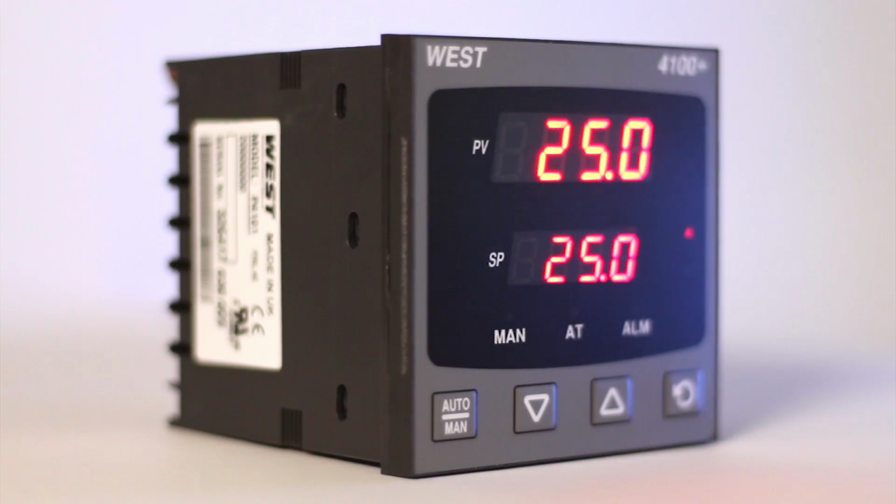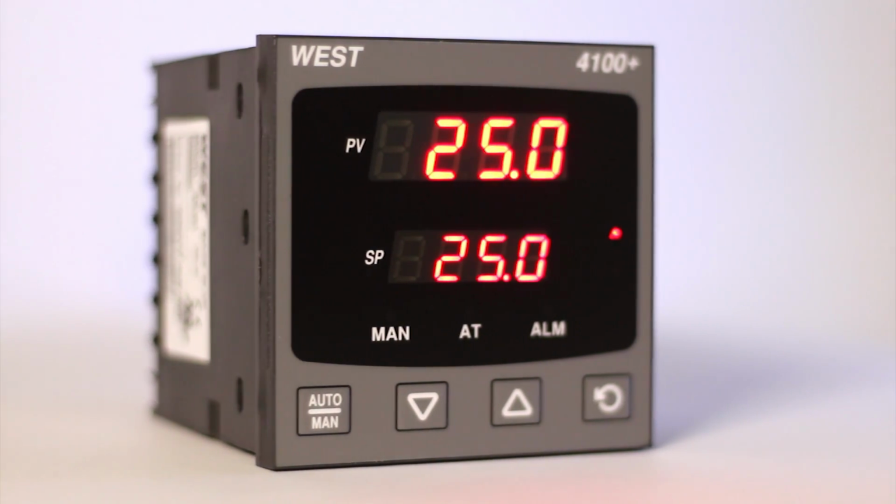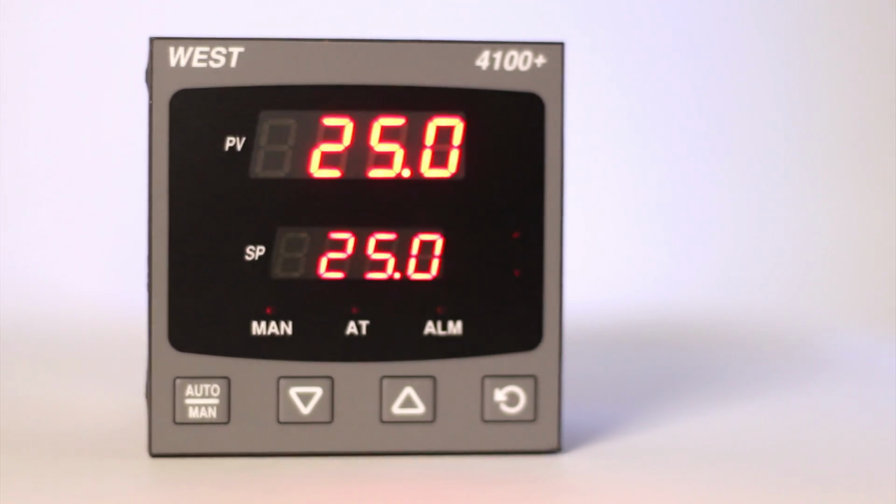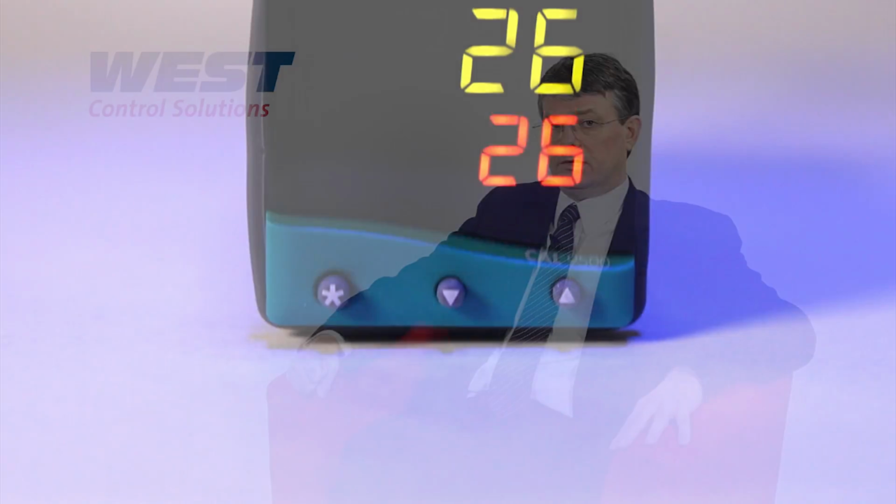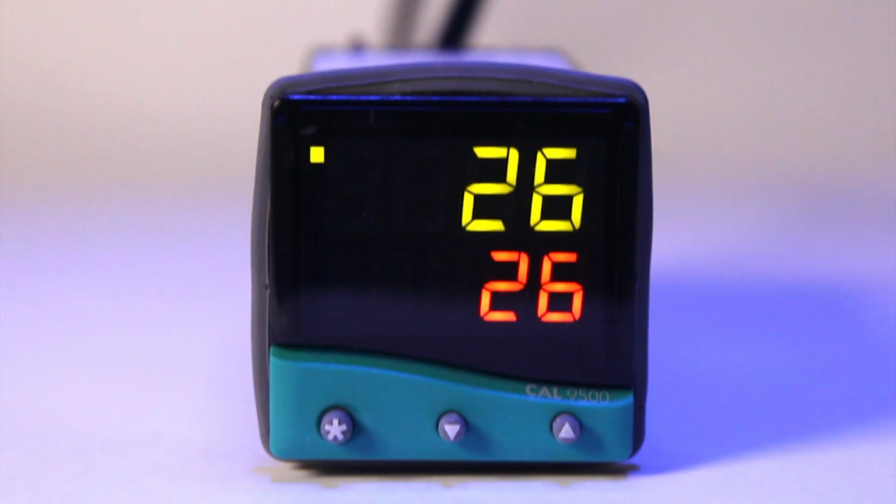So you can use a deviation alarm to warn you if your process is getting too high or if it's getting too low. But what if you wanted to know if it was too high or too low? If your controller has more than one alarm available, you can set one up as a deviation high alarm and the other as a deviation low alarm, so that you'll receive a warning if there is a problem in either direction. If, as in the example I just gave, you wanted alarms at 225 degrees and 217 degrees with a set point at 220, this is exactly what you would do.